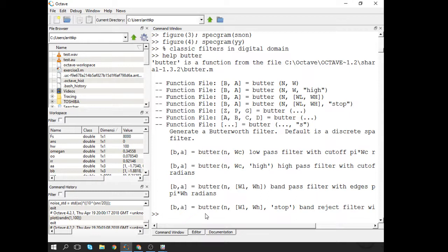And basically, how you start designing is that you have this filter requirements. Remember the box yesterday? So it starts from the requirement box. If it's a flat passband response, then basically it's Butterworth. So you give it a -3 dB point.